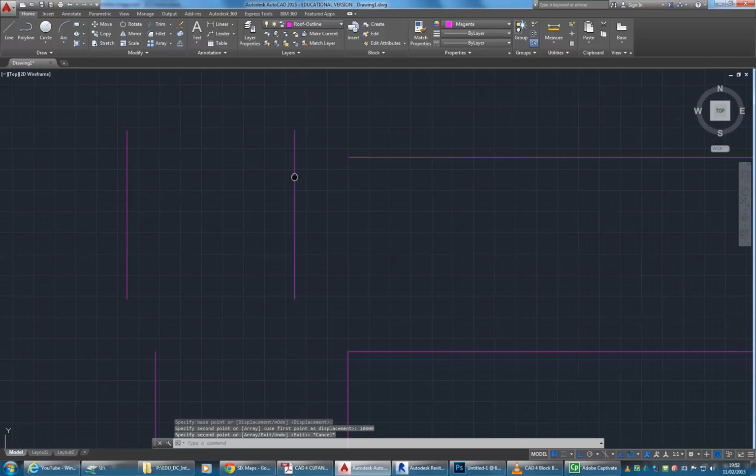And then again, it'd be nice if this distance from there to this corner was a round number. So I'm going to try using measure there and go from that corner diagonally up to there. Right, and so you can see that's a diagonal measurement, but notice that the distance command also gives you the delta Y measurement. Yeah, exactly, the vertical distance. So it's 3.5 metres directly, but vertically it's, let's say, 1600. So again, nice round numbers to work with, make life easier.